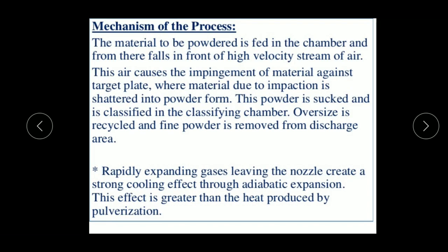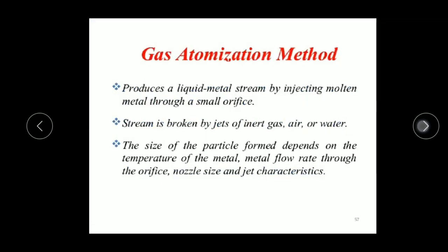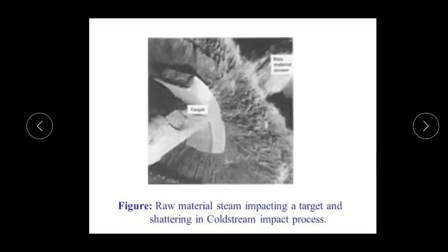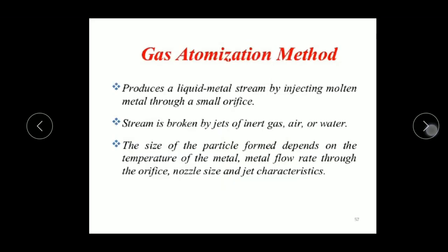The rapidly expanding gases leaving the nozzle create a strong cooling effect through adiabatic expansion. This effect is greater than the heat produced by the pulverization. Dear students, as we can see in the image, the raw material stream is impacting a target and shattering in the cold stream impact process. So let's move on to the next method.